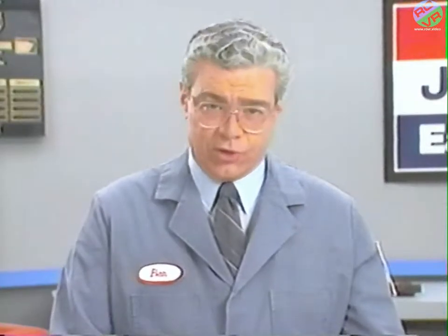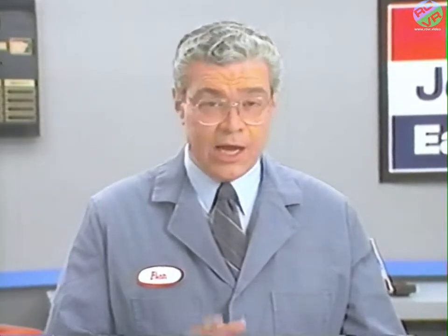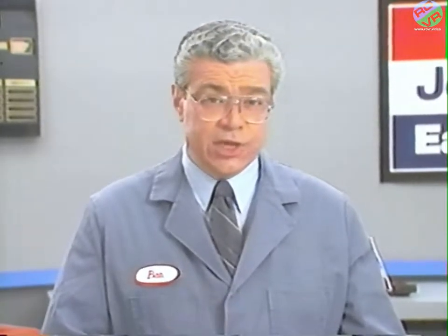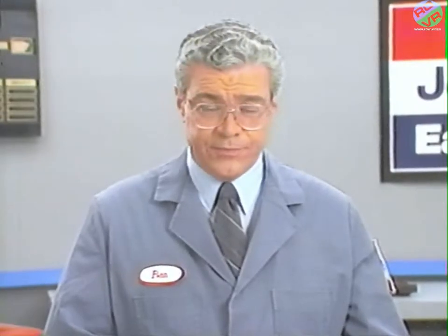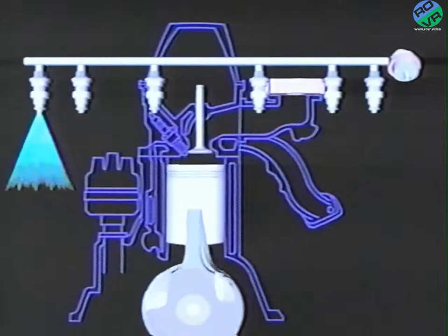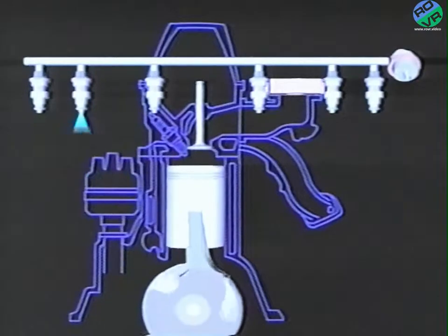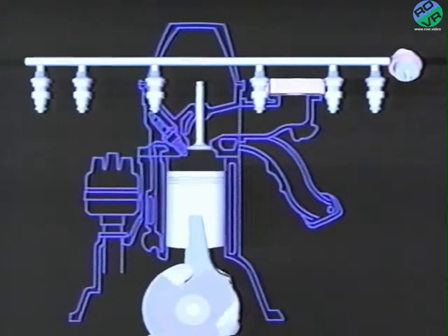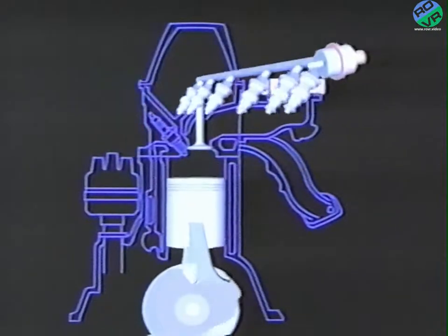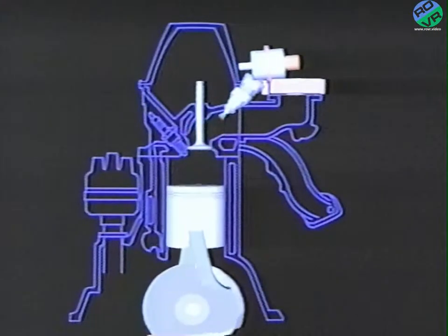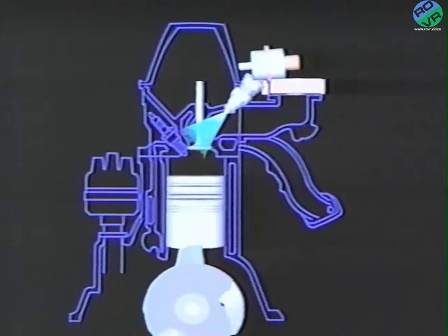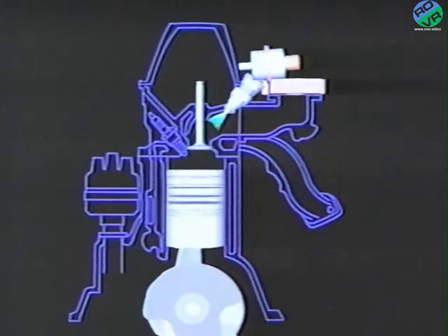The engine controller manages fuel injection in basically the same manner as the Renix sequential MPI system did. However, there are many changes on this 1991 system. Like the Renix ECU, the engine controller fires the injectors in a specific sequence and maintains the optimum fuel-air ratio of 14.7 parts of air to 1 part of fuel by constantly adjusting injector pulse width.